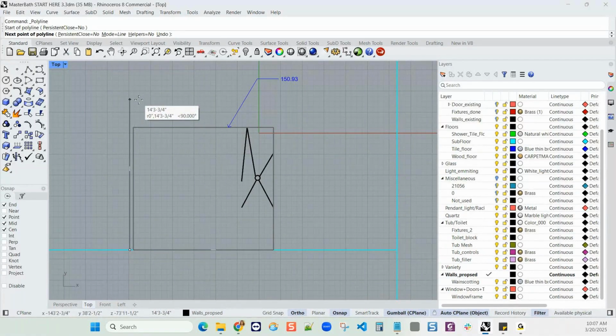And I want to draw a wall that is 12 foot long. So I'll type in 12 feet. I'm going to include the foot mark since the unit in this model is inches. If I don't, I'll get 12 inches. So the foot mark or feet, I would always use the foot mark over typing in feet. But after I get that distance locked in, I'll pick.